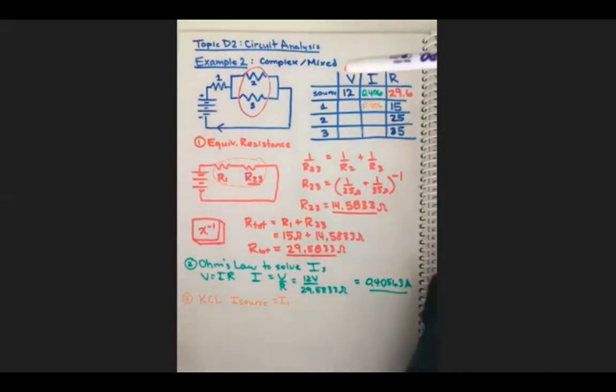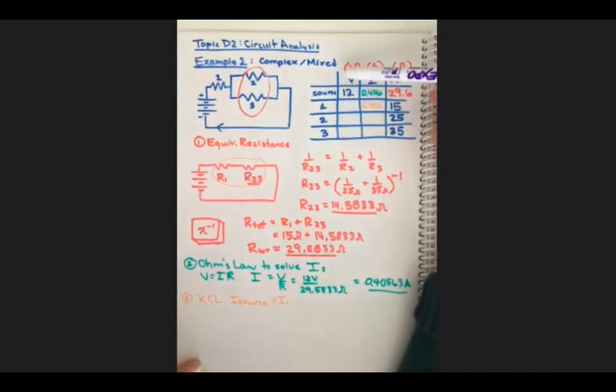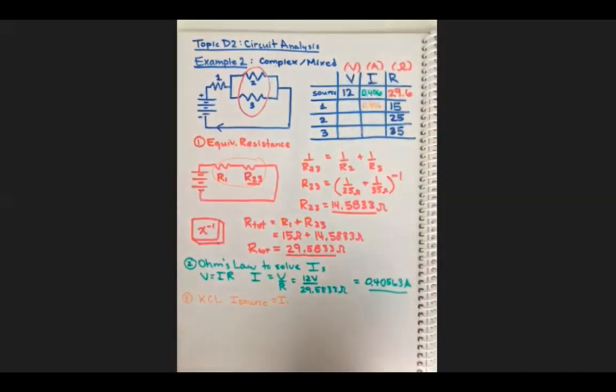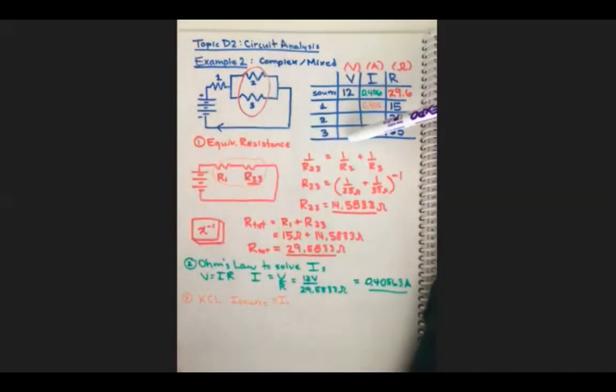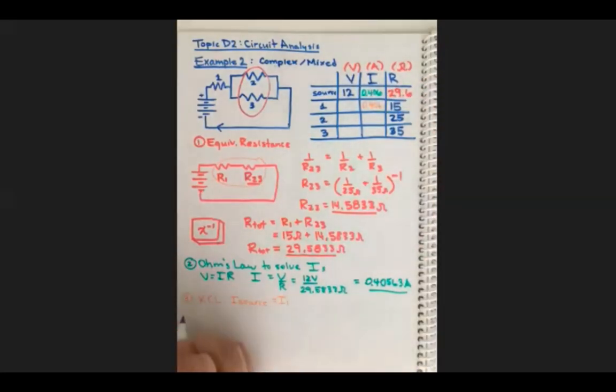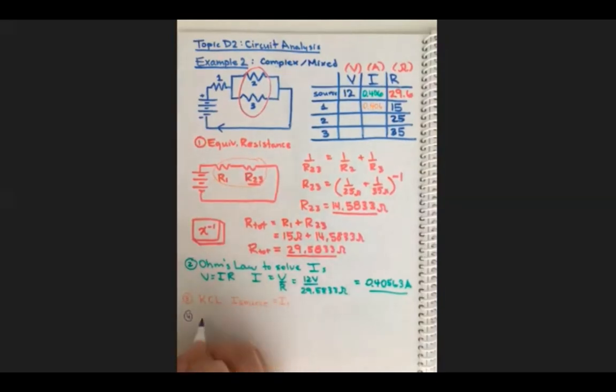So I don't know, can we look at KVL? Vertically, is there anything that we can say? We know that, oh yeah, we can't move forward with KVL for the same reason we couldn't start with it. This is not enough information, just knowing this one. So, oh look, horizontally we can use Ohm's law for V1. That's good. So step 4 is we're going to use Ohm's law to find V1.